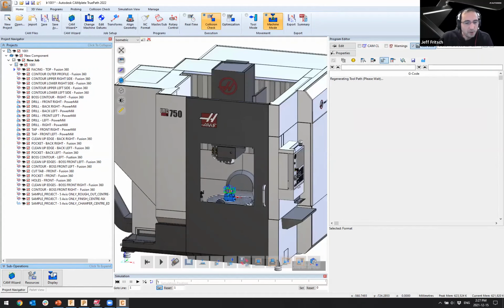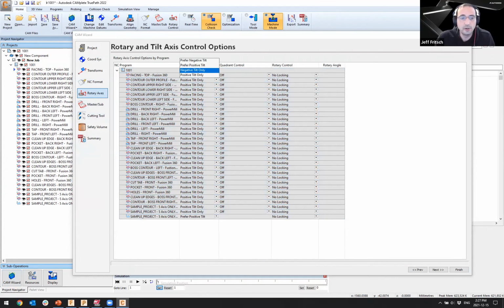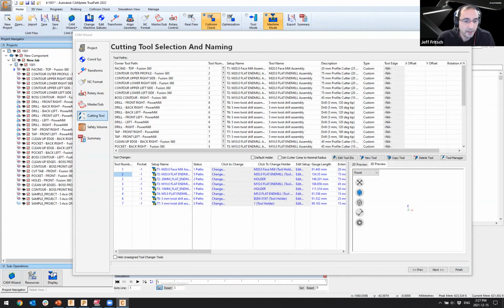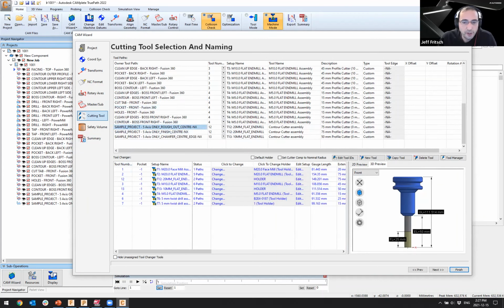Where at that point, we have centralized all of those data points together. We're using the same post processor, and now that we're doing the code generation, you can have full control over this data and how it gets handled. So for instance, here on the tooling side of things, I'm just going to see that, of course, I have my two tools number 2, and I have my two tools number 3. So for an easy solution here, I'm just going to simply relabel some of those tools and see that those changes will now be reflected right away into the code.